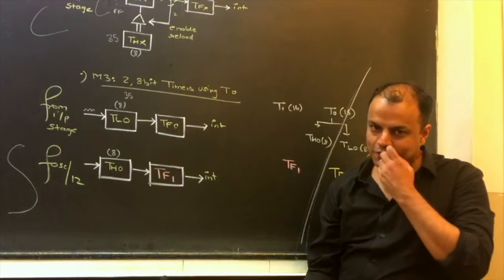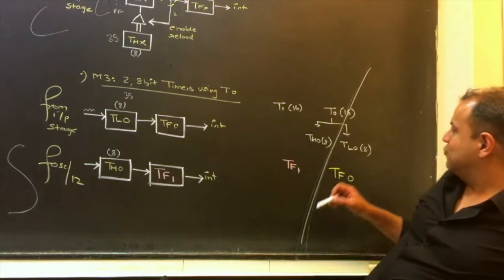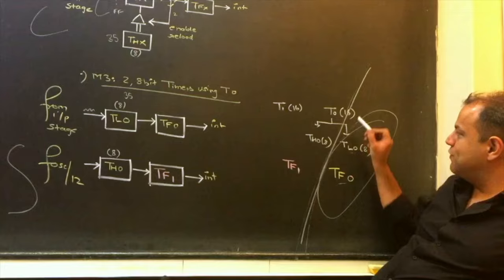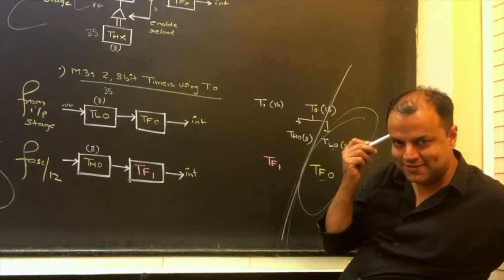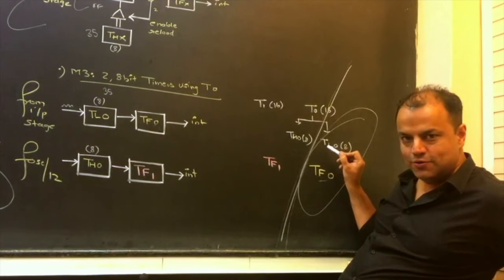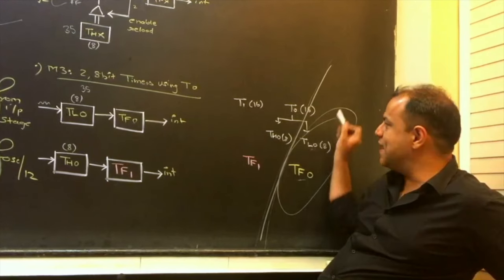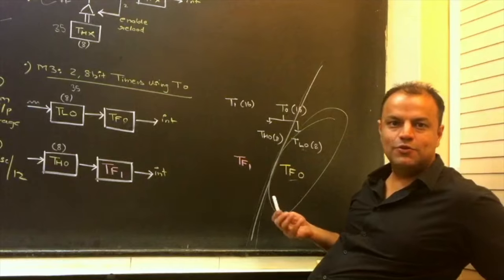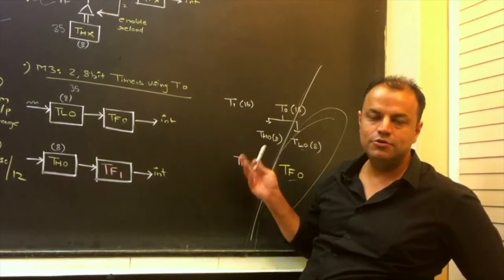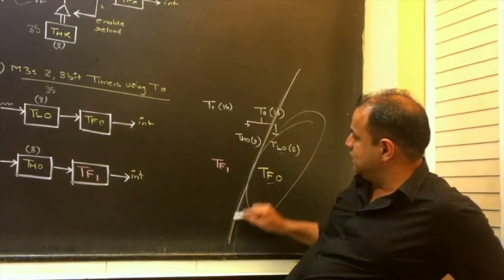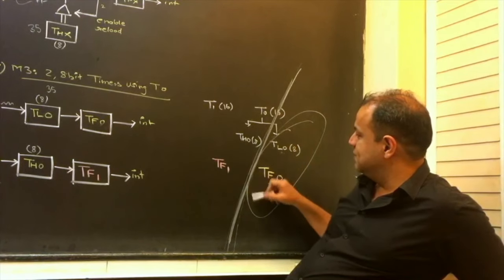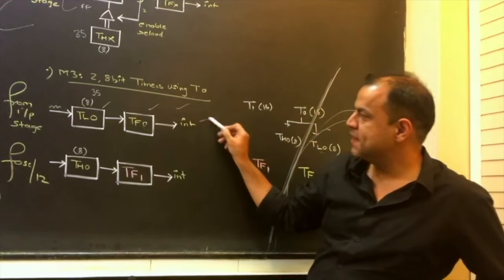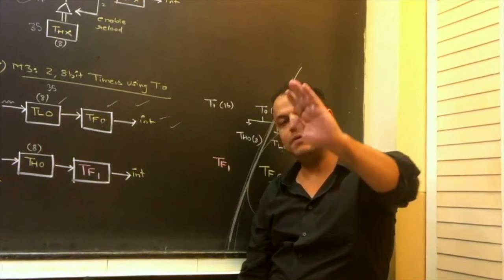Now what did I tell you? To inform the processor, you need a flag. So very smartly, timer 0 lower byte uses the overflow flag of timer 0. Did you even understand what I said? The timer 0 lower byte uses the overflow flag of timer 0. This flag was for the whole timer 0, but it's taken away by timer 0 lower byte. It says I called it first, it's mine. You were lazy, not my fault. Now you see this line, don't cross it. Don't come to me. This has become my flag. So timer 0 lower byte uses the overflow flag of timer 0 and has successfully become an 8-bit independent timer.